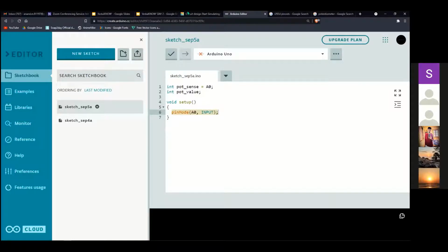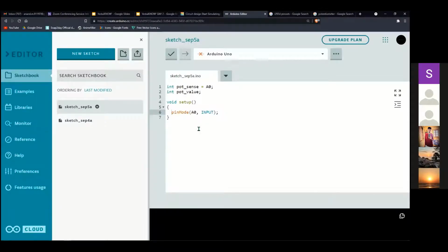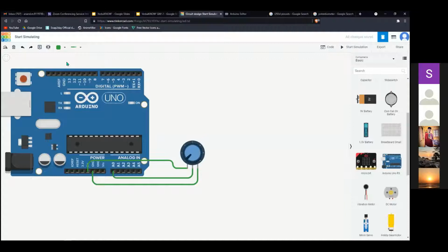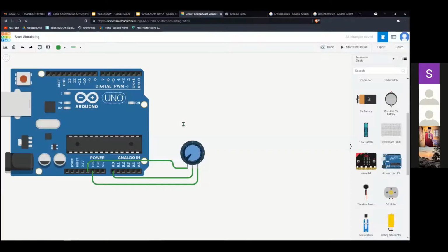If you are changing the unlock signal, like if you don't want to measure it on A0 and want it on pin number 2, 5 or 7, then you need to mention this statement at the beginning of your void setup. The pins numbered 0 to 13 are the GPIO pins, which are by default considered digital pins, and you can also convert a digital pin into an analog pin by naming it like this. As we are going with the dedicated analog pins, we don't require this, so for now I'll just make it a comment.